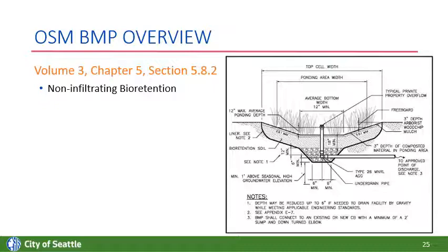Even though the soil might not be getting very good infiltration, there are no hazards to the property or downstream property, so we can consider elimination of the impermeable liner underneath. The sizing factors and the figures have been updated, and clarifications have been added for the setbacks. The design criteria for the hydraulic restriction layer, liner, and bioretention soil mix have been clarified.